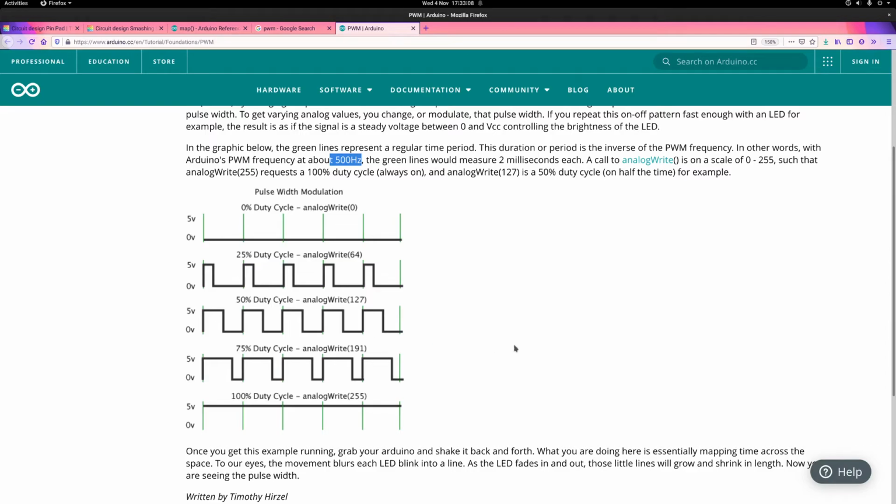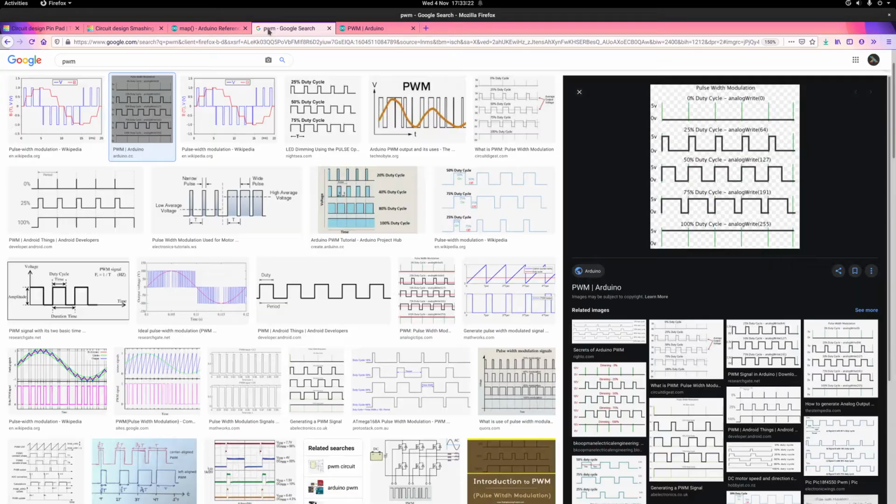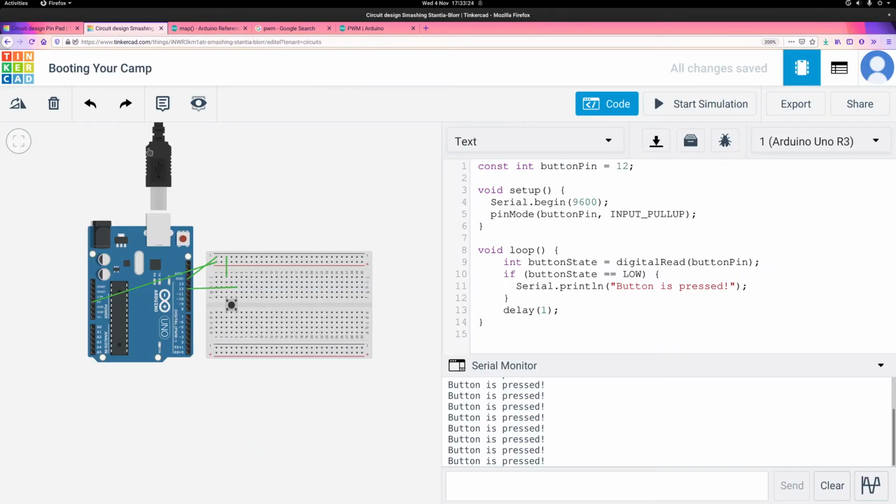So you can think about this as a way for us to turn our LED on and off smoothly using the Arduino. We can go from faking 0 to faking full voltage. Well, actually, these are 0 and 5 volts, but we're faking the in-betweens. Lovely. So that is how that works. Here's where we were.